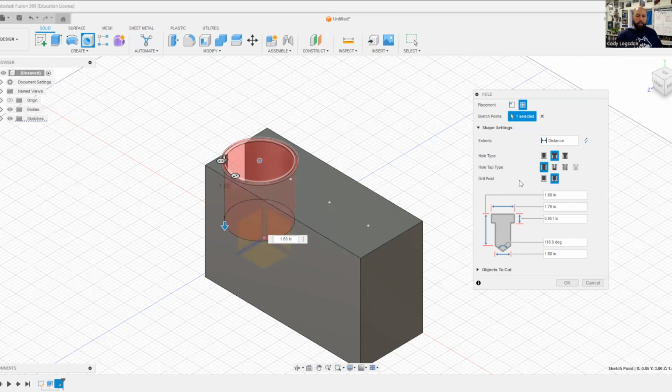The drill point, if you're reading this off of the instructions, you won't be able to see what type of point it is from the side view, but you could kind of tell from the top view. If you have the smaller instructions, the half sheet in our notes, you'll see the side view and you'll see that the drill point is actually an angle point. So from there, now I just need to add in all of my dimensions. The first dimension that I'm going to look at, if I'm reading my holes notes correctly, is the entire height.